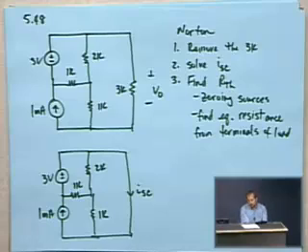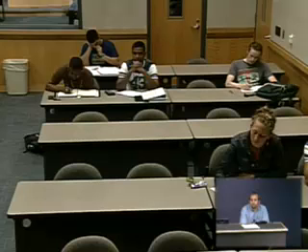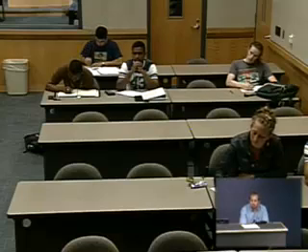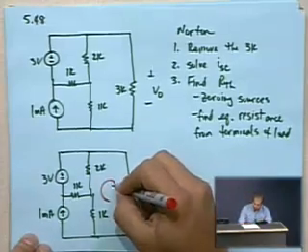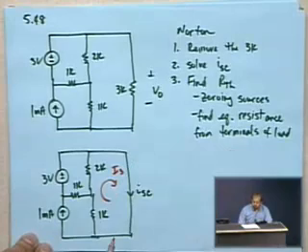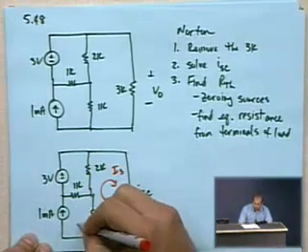So what can we do? We need to solve for this current, so how might you do that? Yeah, a mesh analysis is probably a pretty good way to deal with this. So let's introduce 3 mesh currents, and let's do them conveniently so that I3 will give us the short circuit current.